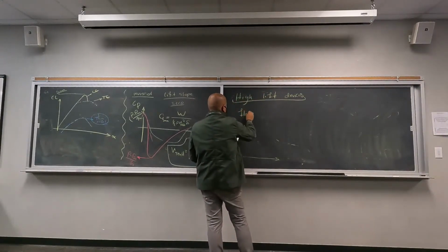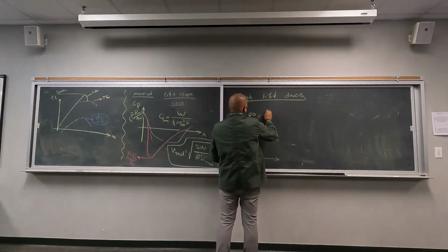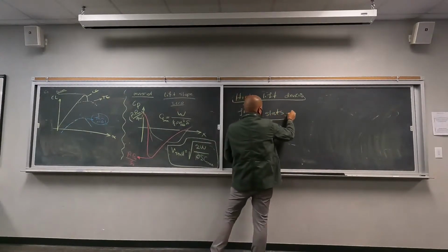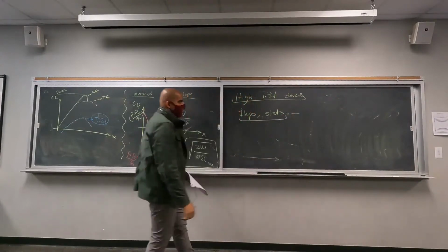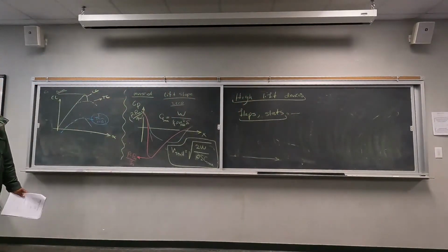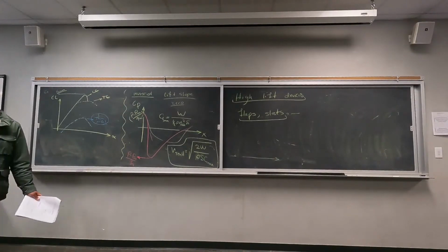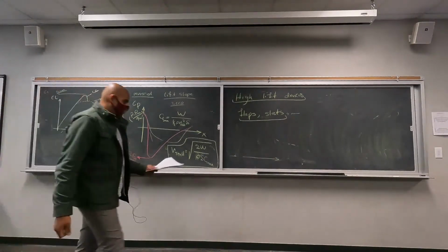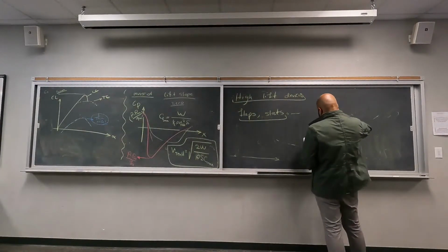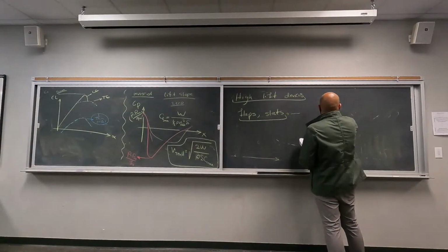Flaps and slats, and there are a couple of more mechanisms. So by introducing this, we will be able to play with the flow pattern on the airfoil, which means that we can delay the flow separation, and we can also change the camber. One of the most traditional types of flaps and slats is the trailing edge flap.